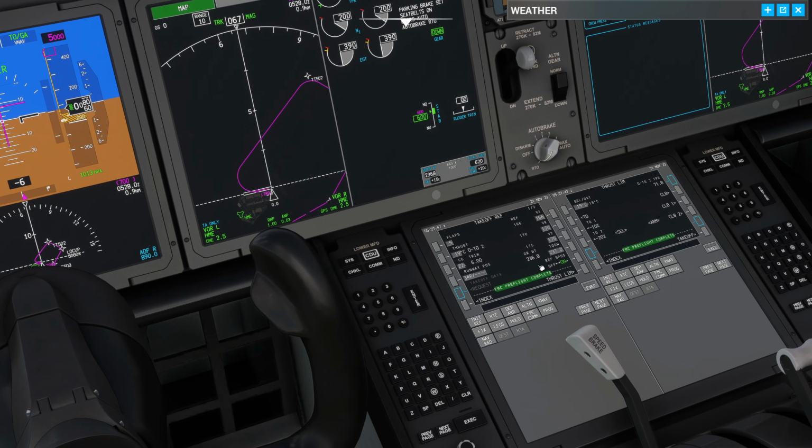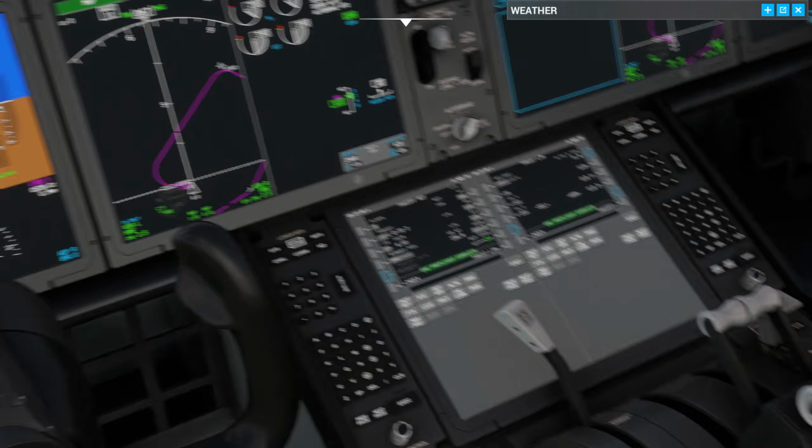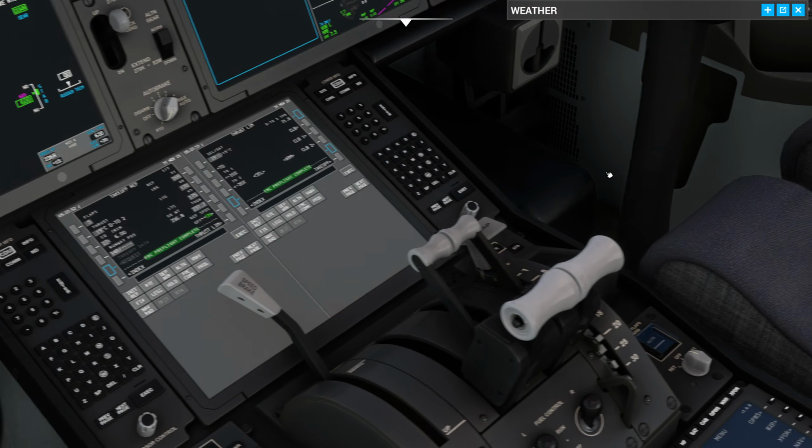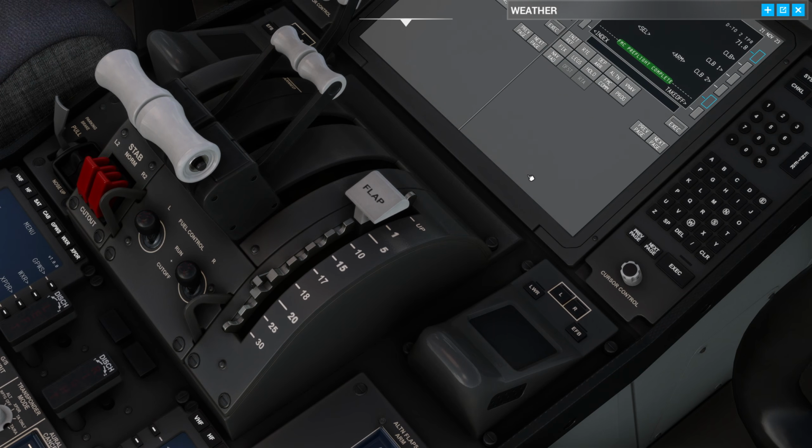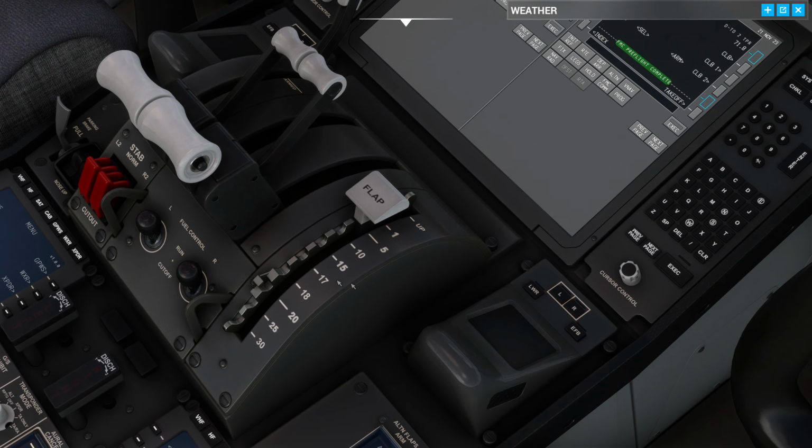And of course, we need to have the flaps set. So we've said flap 5, so let's set 5. Now, look at all these settings. Your settings may look different depending on which version of the 787 you're flying. The 787-8 has the simplest flaps. It goes from up, 1, 5, then 15, 20, 25, 30. But if you're in the -9 or -10, you're going to have these other settings: 10, 17, 18, and 20.